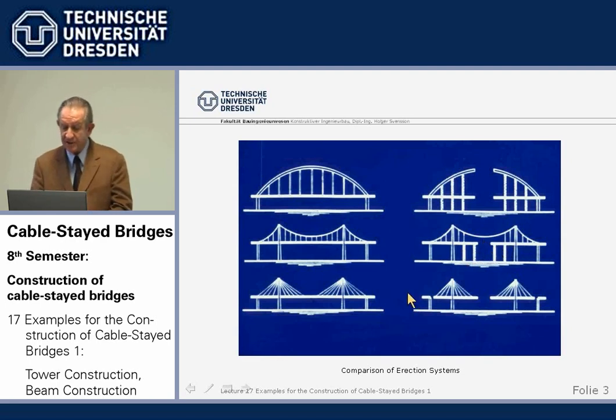Contrary to that, in a cable-stayed bridge, in the final stage, the load is carried up by the cables and back here, and the horizontal component is, as a compression force, carried in the beam. And the same is true for intermediate construction stage systems, where we also have the same flow of forces.